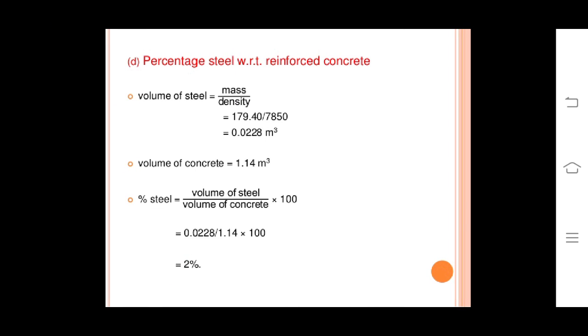Now this example is a complicated example of a heavily reinforced beam. For solving such kinds of problems, we have to first bifurcate the type of steel bars provided for the particular component, and after the shapes and diameters of the bars are bifurcated, then these shapes and diameters are entered into the bar bending schedule for easiness in the calculation of the total weight of bar.